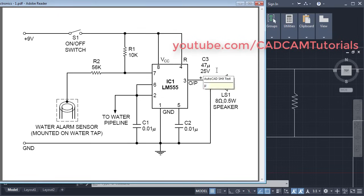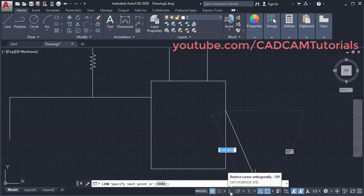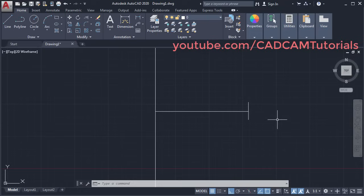Then next is this side. We will create this line, then we will create this capacitor. Click on line, take your cursor to this endpoint, take it below, click, take it on the right side, make ortho on and click and press enter. Press enter to repeat the line command. Take your cursor to this endpoint, take it above, click, then take it below and click and enter.